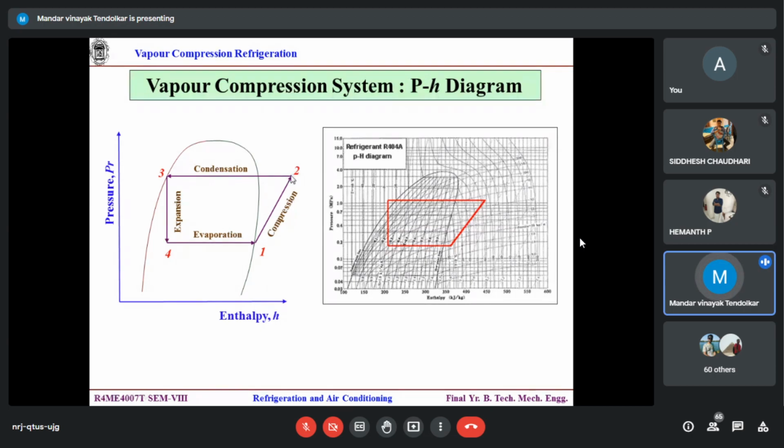This is my isentropic compression, starting from the saturated vapor, then superheated vapor. I can see that it is outside, on the right hand side of the saturated vapor, so that means this is superheated, simple. These are the temperature lines you can see. Then horizontal, and then moving like this. So naturally this temperature line and this temperature line are different.